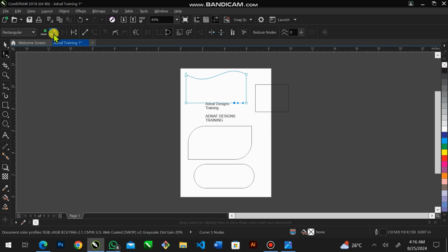So you'll be using this to control it. You can also double click here to create another one. You can create as many as possible. Double click, make sure this node is selected like this. Convert to curve, drag it in. Delete the node. So after then click here to get this. Then you can take it in or bend it as you want.